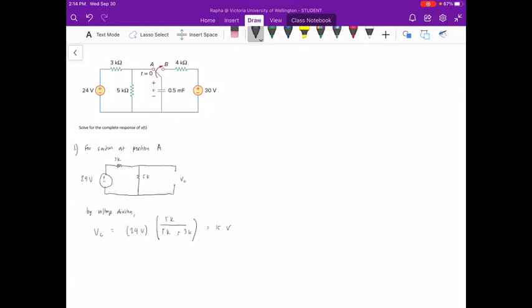And our VC is actually equal to our VO, or voltage at time equal to 0, so we will just write again the 15 volts. This is because the capacitor voltage does not change immediately. So right before moving the switch to position B, the VO, or the VC, the current capacitor voltage is equal to 15 volts. So the second part is for switch at position B.